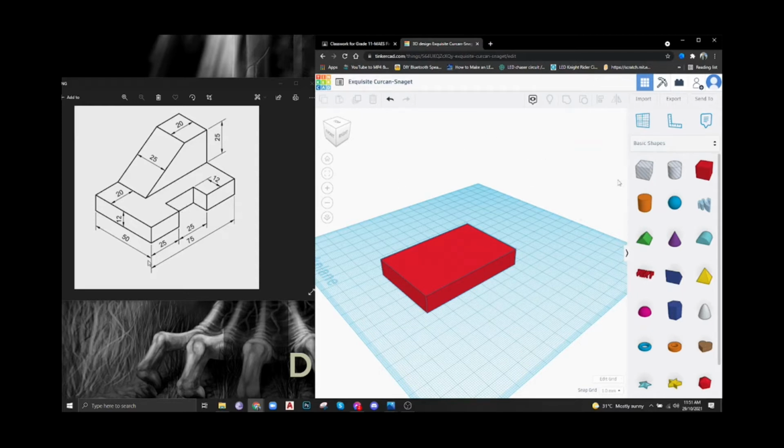In order to make a hole, just use this part here, this box, and I'll just make this space here. Knowing this is 25 and the space is 12, then the height still is 12. So I'll make a box with those dimensions. 12, 25, and just change the height to 12 and enter. So that's the object already.